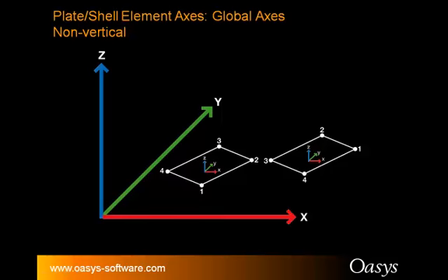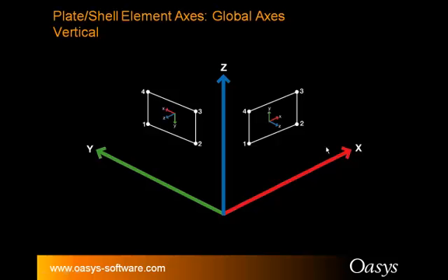But if you've got walls and so on, then the global axes aren't going to work because they're then parallel to the z-axis, and it's worthwhile defining your own wall axis sets to make sure your elements are correctly aligned. In terms of moment output and that sort of thing, it won't make too much difference, but when you come on to reinforced concrete design with GSA, this will make a huge difference because the reinforcement is oriented by the local x and y axes.